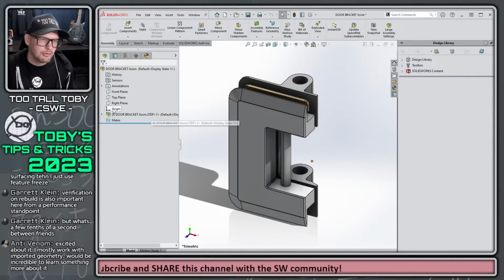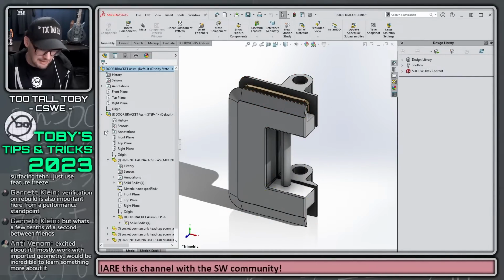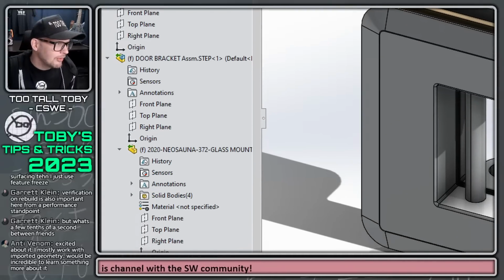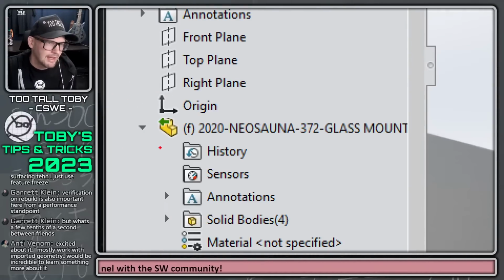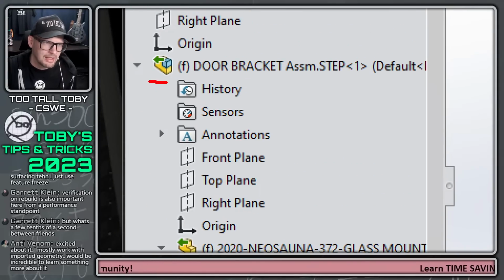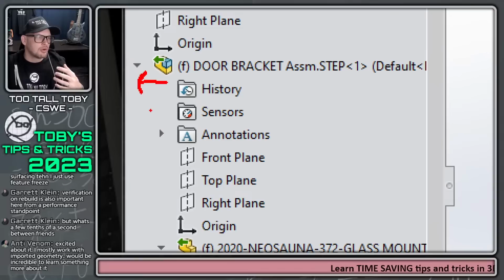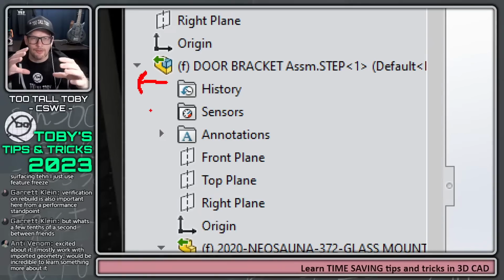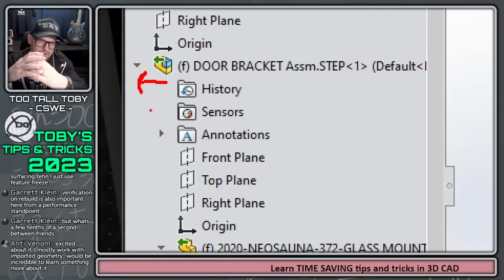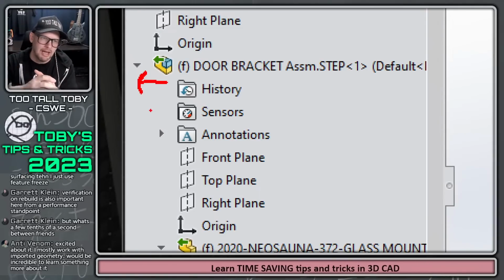directly in SolidWorks. The display that you'll get when you do this looks something like this. It may look a little bit unfamiliar. It's like the part file with a little green arrow sticking over to the left, or the assembly file with a little green arrow sticking over to the left. When you see that, that means that you've got 3D interconnect turned on, and it means that you're placing an external file source into a container, and then essentially you're viewing that container inside of the SolidWorks format.